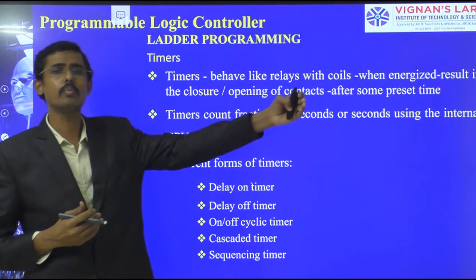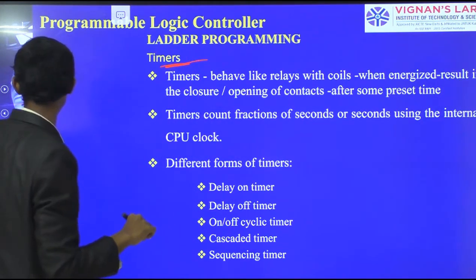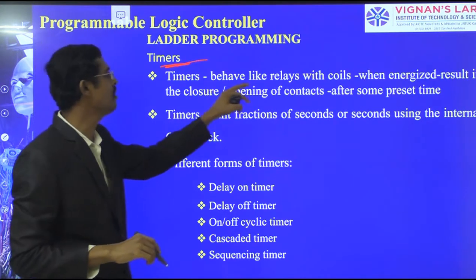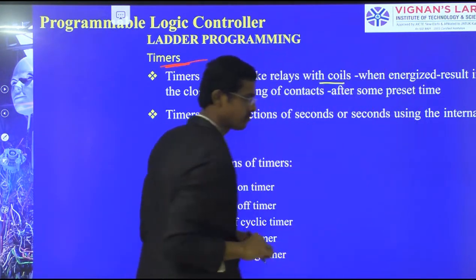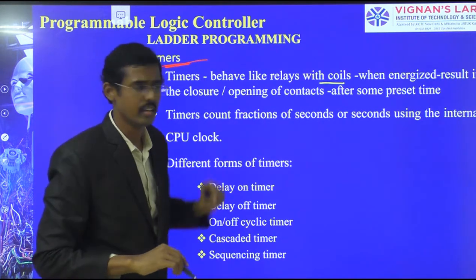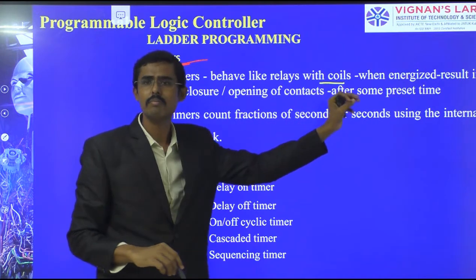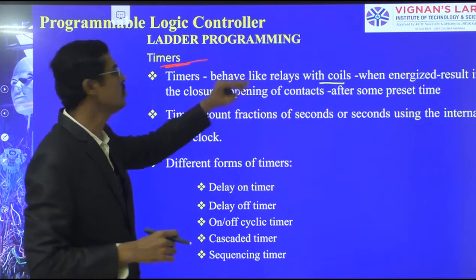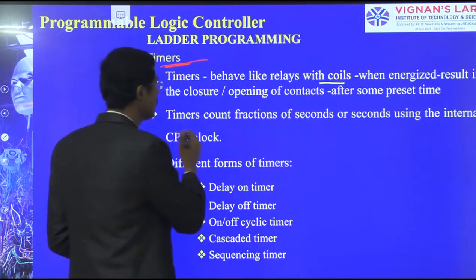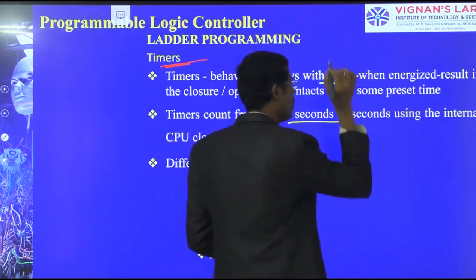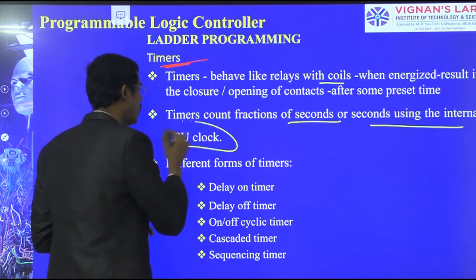I want to incorporate some other points about timers here. Timers behave like a relay with coils: when energized, they result in the closure or opening of the contacts after some preset time. The timer counts fractions of seconds or seconds using the internal CPU clock.